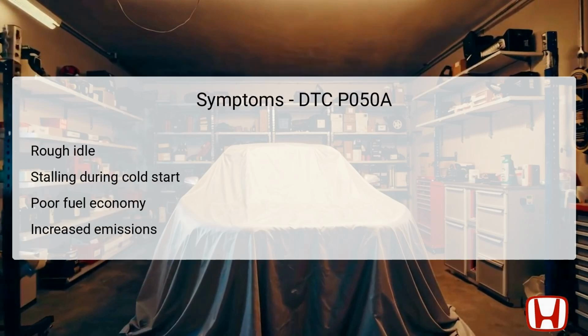The symptoms associated with the DTC P050A can manifest in various ways. A rough idle is a common occurrence as the PCM struggles to regulate idle conditions effectively. Drivers may also notice that the vehicle stalls during cold starts, indicating that the fuel-air mixture is not being managed correctly right after ignition. Such failures can lead to poor fuel economy, as the engine may consume more fuel due to an improper air ratio, resulting in less efficient combustion.